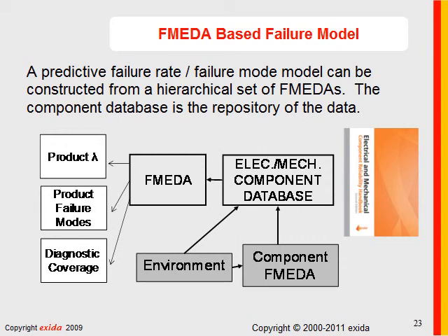Environments can be categorized. There are IEC standards showing you the typical and worst case numbers for environmental variables for the industrial process control environment. Given those standards, environments can be characterized, and the environmental variables can be fed into a component level analysis. If it's a simple component, like a resistor, many analytical models are available.